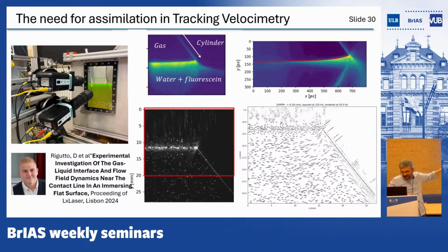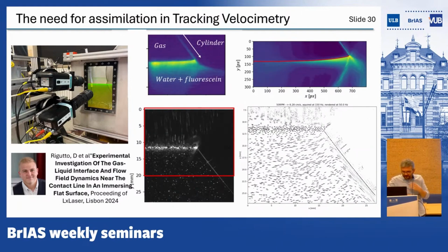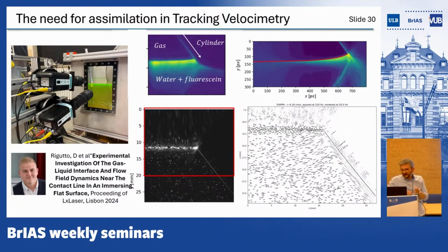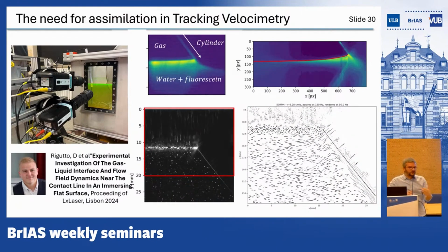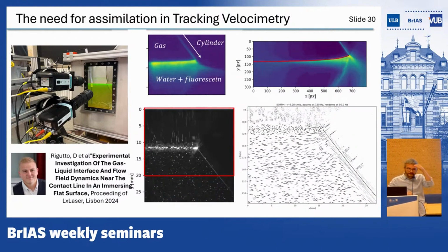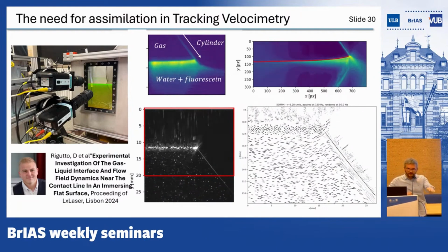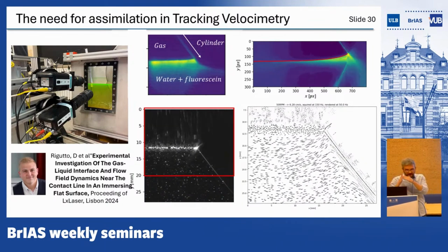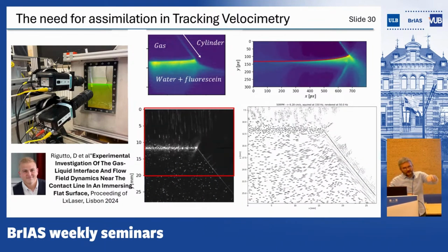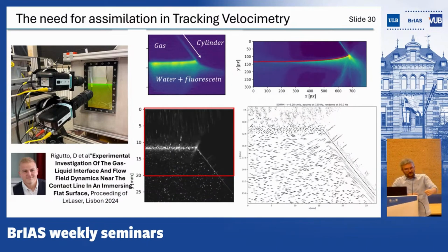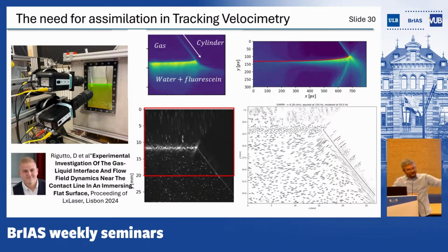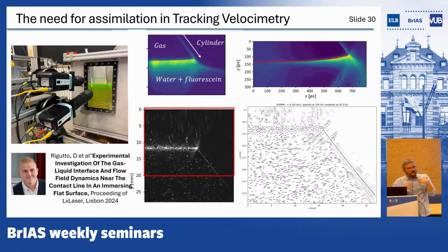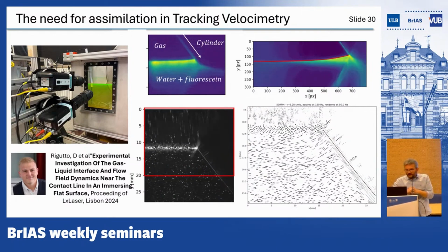Now, in galvanization, it's a very important configuration, because what can happen is that if your strip goes at a certain speed, usually the strip is not perfectly flat. There is always some level of roughness. You can entrain air because the contact line is not stable, and this air can remain on the plate if the bubbles are sufficiently small and come back when you pull the strip out of the vat and create defects. So here the idea was to study how this process is happening.